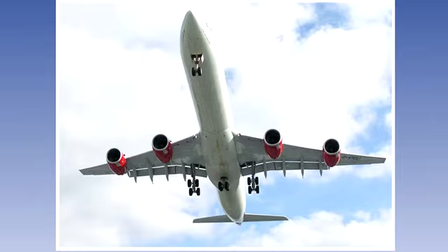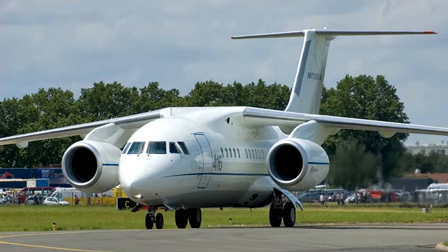The body gear itself may actually still be steerable. This helps to reduce the turning circle and reduces the effect of wheel sideways movement or tire scrubbing, which affects multiple wheel landing gear systems. A number of aircraft are designed to operate in the dual freight and passenger carrying roles, especially from airports with limited resources. This has resulted in high-wing monoplane type aircraft where the floor of the aircraft is as close as possible to the ground for ease of freight loading.